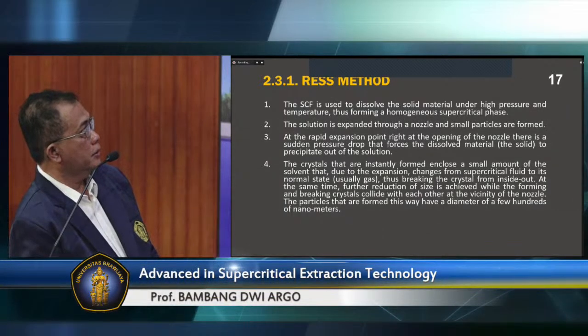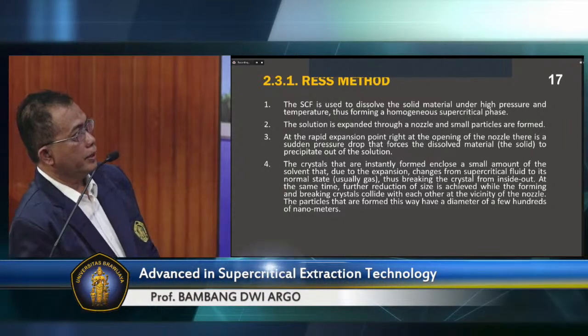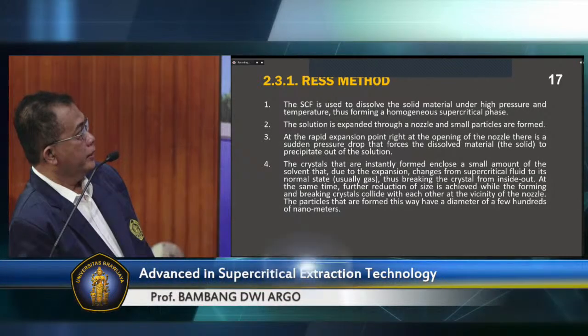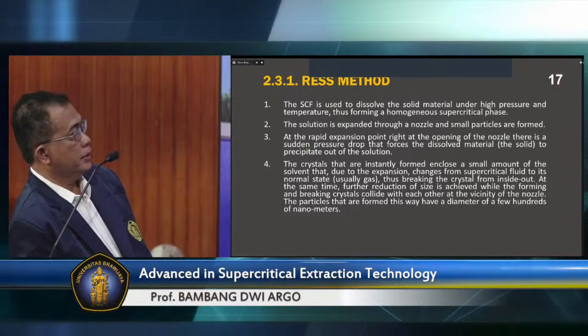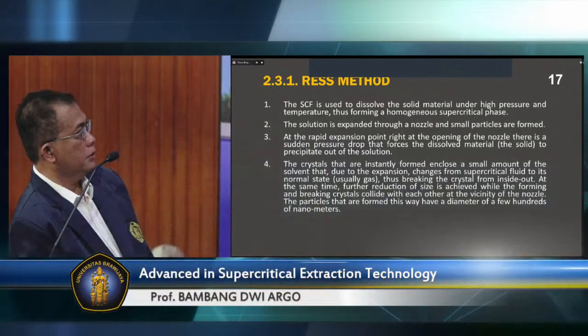The second, the solution is expanded through a nozzle and small particles are formed. And then, at the rapid expansion point, at the opening of the nozzle, there is a sudden pressure drop that forces the dissolved material to precipitate out of the solution.